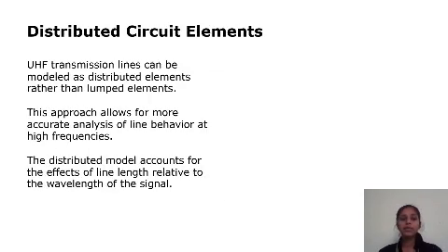Distributed circuit element. UHF transmission lines can be modeled as distributed elements rather than lumped elements. This approach allows for more accurate analysis of line behavior at high frequency. The distributed model accounts for the effects of line length relative to the wavelength of the signal.